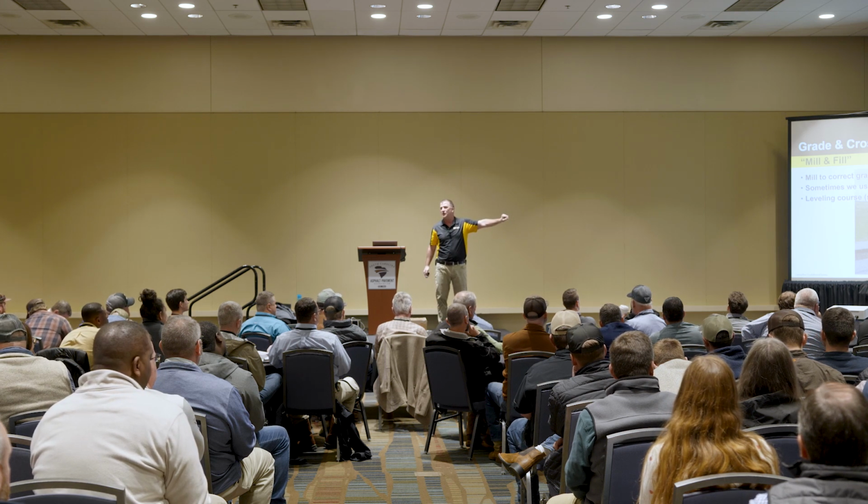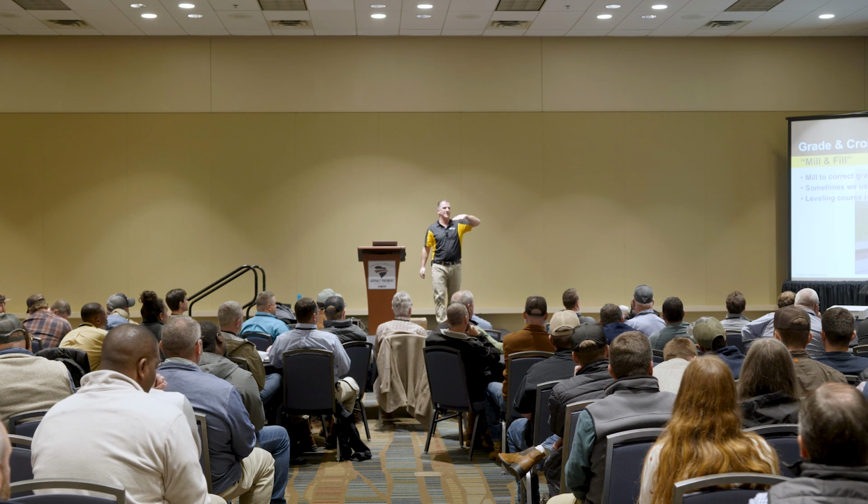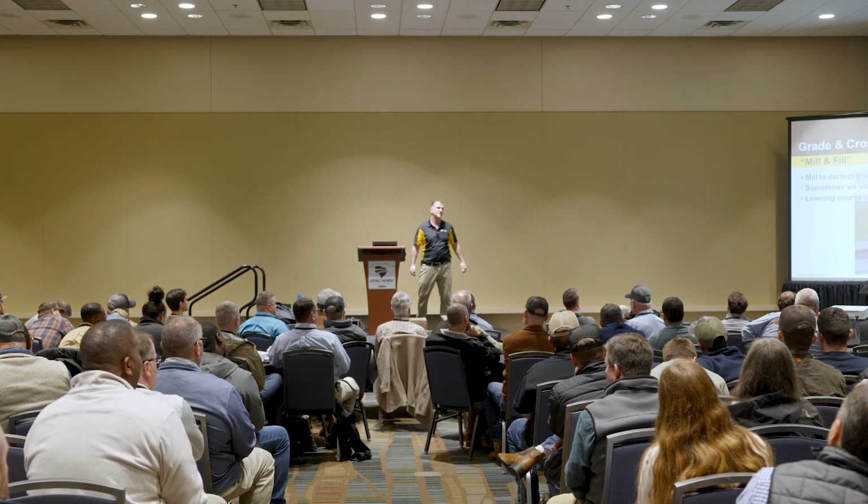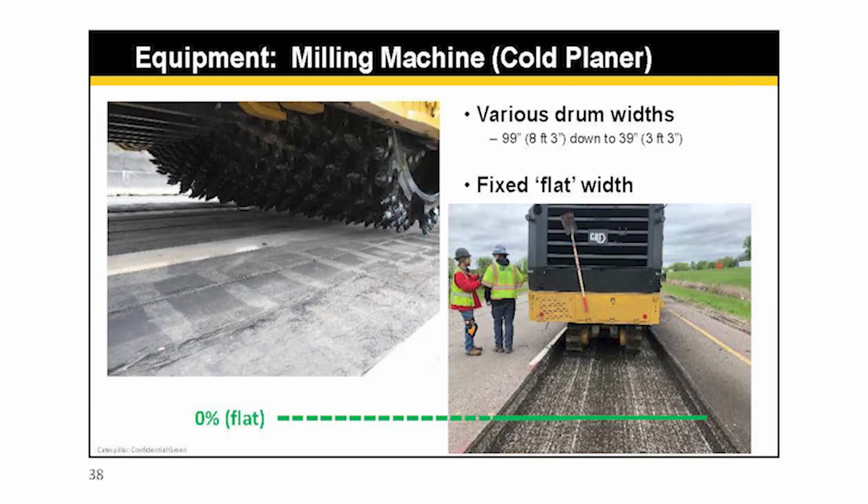But a lot of times, we come in and we have to do a level course or scratch course to get that base at the right grade, and then we come in and maybe do a top lift. So there's a lot of different scenarios. Just one slide here on the mill.